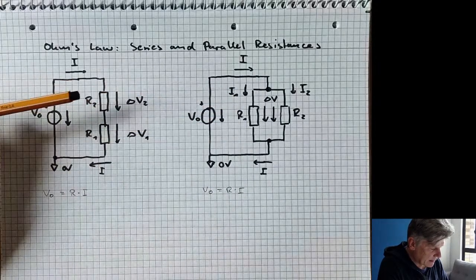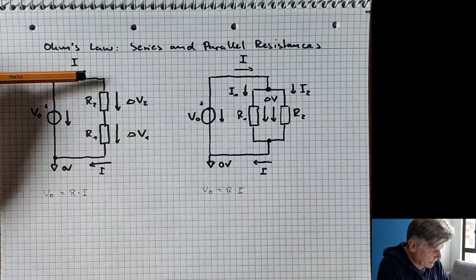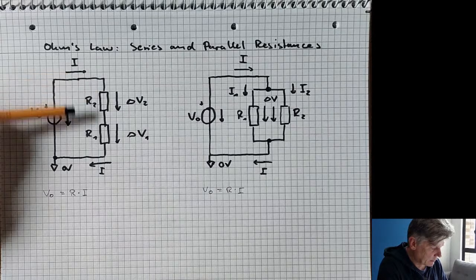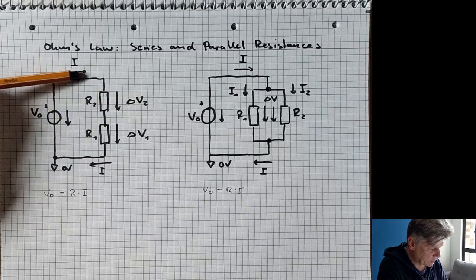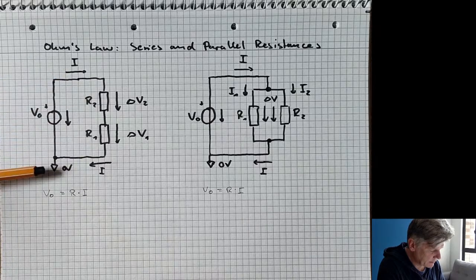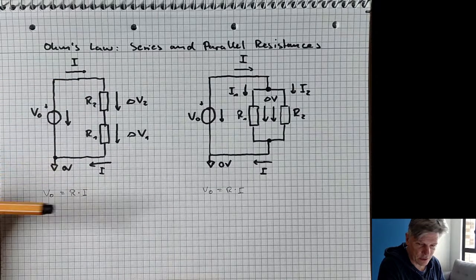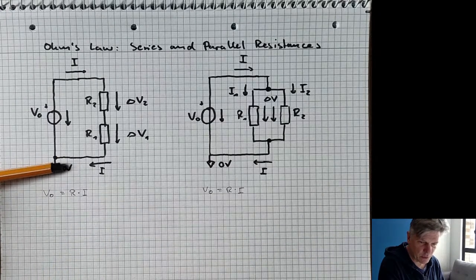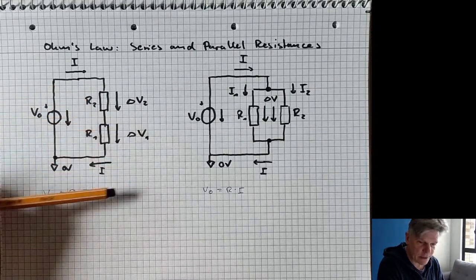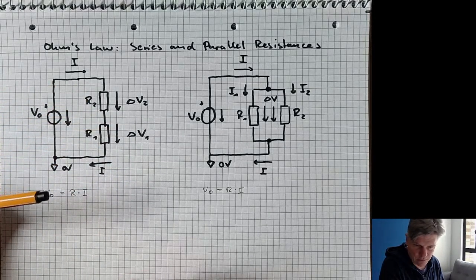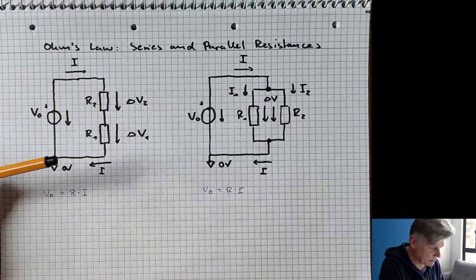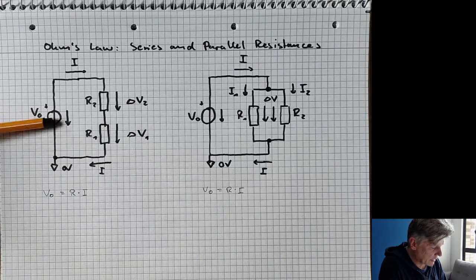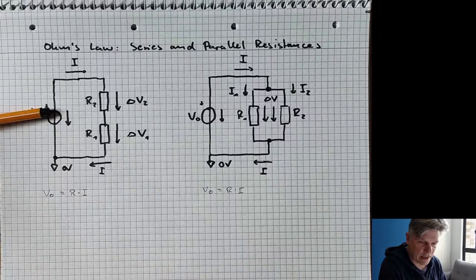And you can see that we have a potential difference here coming from the voltage source. So let's say, for example, plus 5 volts. So this potential might be 5 volts higher than that one. And we define this to be 0, but this is just when we do calculations. We want to convert everything to absolute numbers, so we need a reference potential. We could put it everywhere, and the results would be the same, right? You would come up with the same resistance, for example. But it's convenient to choose a point which is connected to the negative terminal of the ideal voltage source.